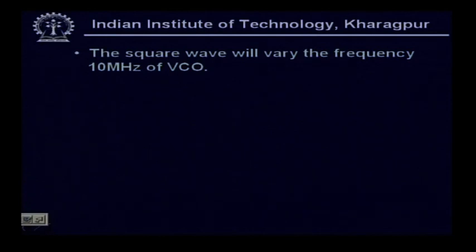because the square wave we cannot give directly, we will smoothen it, we will convert it to DC. You see here, we have the unbalanced voltage which is coming from the strain gauge, or I should say it is a Wheatstone bridge.